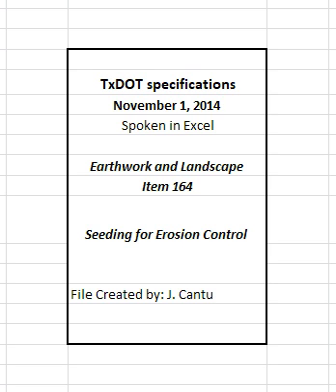2.2 Fertilizer. Use fertilizer in conformance with Article 166.2, Materials. 2.3 Vegetative watering. Use water that is clean and free of industrial wastes and other substances harmful to the growth of vegetation. 2.4 Mulch. 2.4.1 Straw or hay mulch. Use straw or hay mulch in conformance with Section 162.2.5, Mulch.